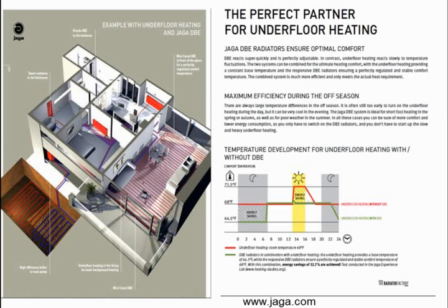Well, up until recently, all we really had was the basic stuff that was really designed to be used at high temperature systems. Originally, when fin tube baseboard came out, it was designed to work on boilers in a 180, 200 degree operating range. Didn't get much output of performance from that when we started talking about the lower temperatures, but there are some products and manufacturers that are addressing that market right now, and one of them is this company called Yaga, is how it's pronounced, I think.